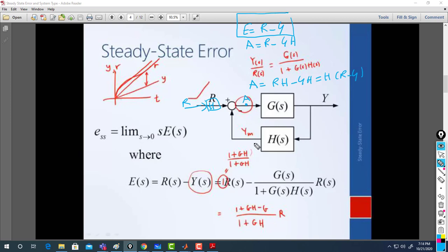It's not the actual output voltage, it's the output of the sensor, and at the end the output of the sensor is a voltage. If you want to compare, you can compare voltage with a voltage. Right, that's what we did in the milestone too, we put K. So you compare voltages. You cannot say 4 meters in this case, so you need to convert the 4 meters to a voltage. So you put the sensor dynamic to convert the 4 meters to 0.4 volt.